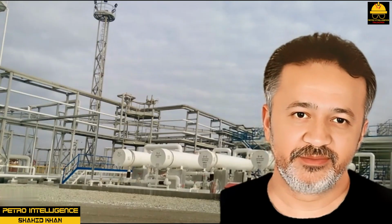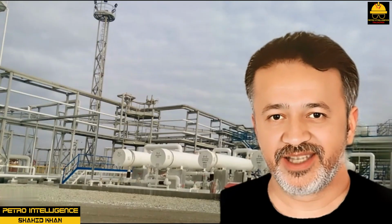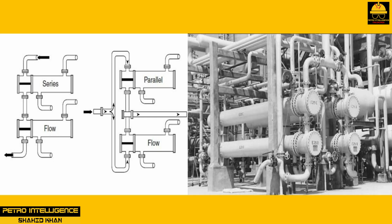Parallel and series flow. Heat exchangers can be connected in a variety of ways. The two most common are series and parallel, as shown in picture. In series flow, as shown in picture, the tube side flow in a multi-pass heat exchanger is discharged into the tube side flow of the second exchanger. This discharge route could be switched to shell side or tube side depending on how the exchanger is in service. The guiding principle is that the flow passes through one exchanger before it goes to another. In parallel flow, the process flow goes through multiple exchangers at the same time.